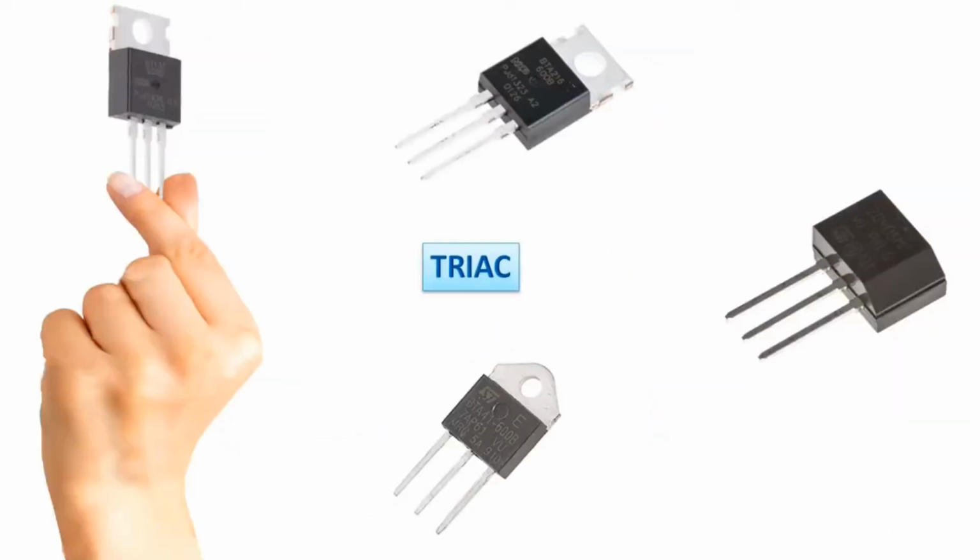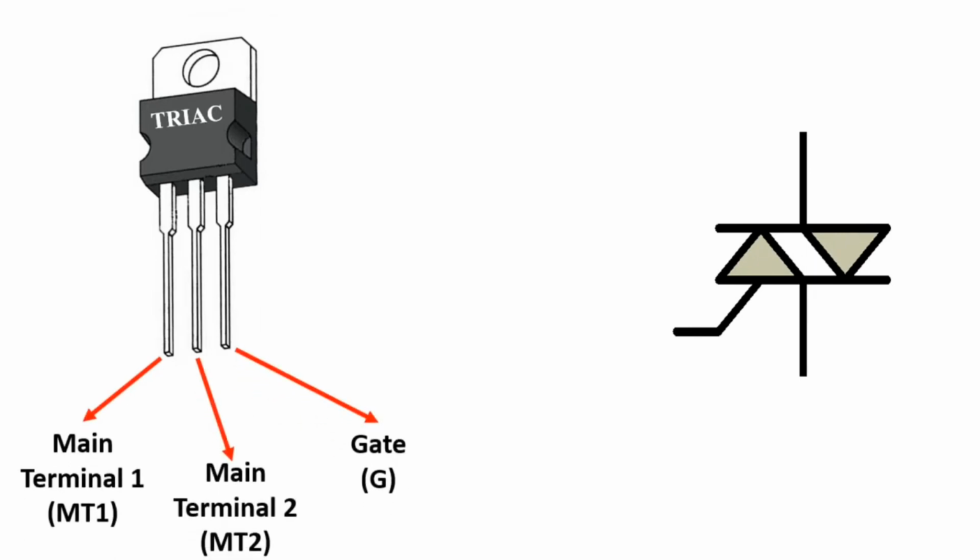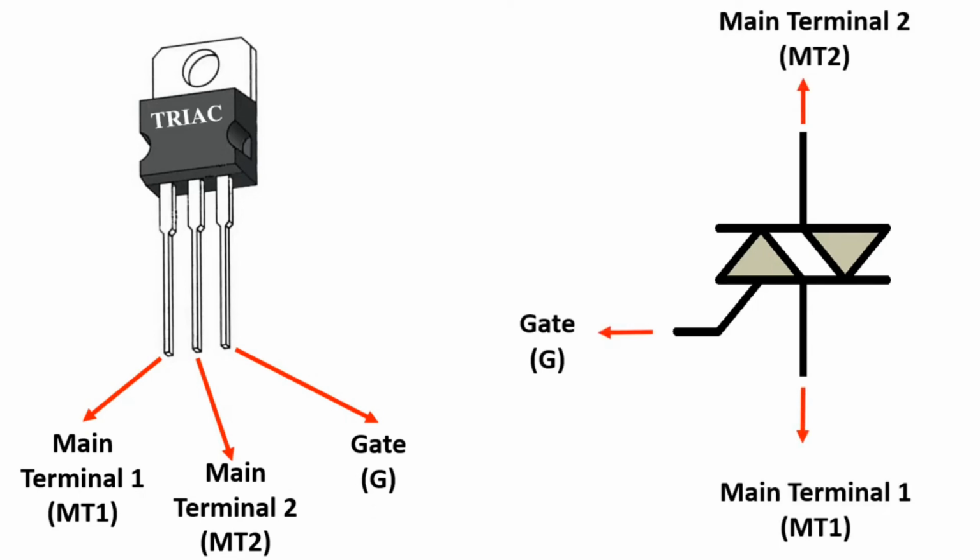Triacs are similar to thyristors. The abbreviation triac comes from the initials of the English words triode for alternating current. It is actually formed by the reverse connection of two thyristors to each other. As such, they are used for switching purposes in AC power electronic circuits. Pin names differ from thyristor. These have 3 pins, and the pin names are as you can see here.